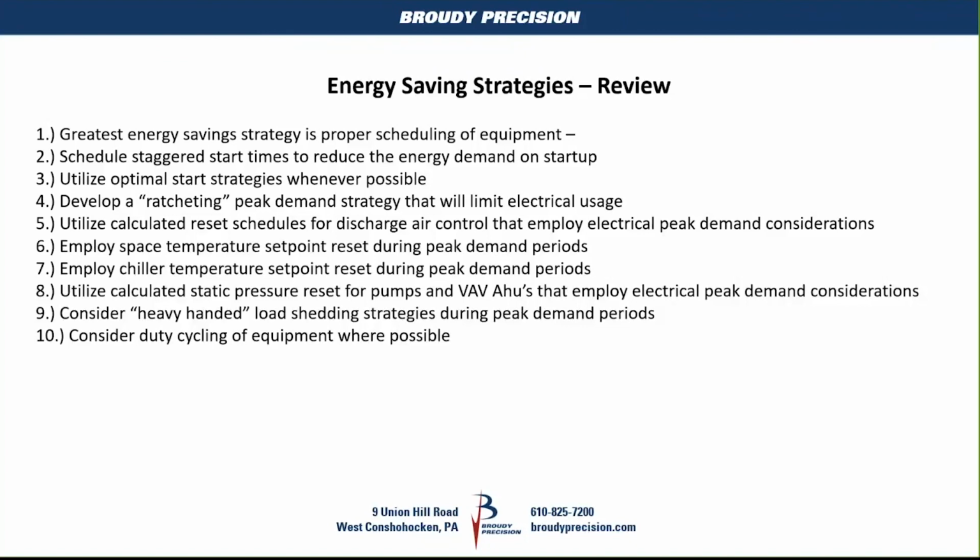And some of those things are by doing set point increases, very gradual. It's built into a lot of, Honeywell has it built into their demand limiting. It's demand limiting, DLC, I think it's abbreviated for. But you're essentially coming up with, hey, we're in a high demand situation here.